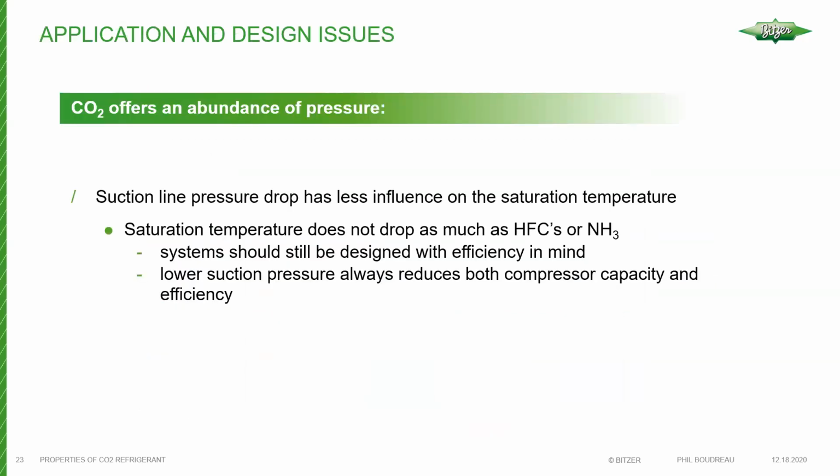CO2 offers an abundance of pressure, and that may sound strange, but over the next couple of slides it'll make more sense. Basically, think about it this way: suction line pressure drop is going to have less influence on the saturation temperature. We could see more pressure drop in the suction line before we see a drop in saturation temperature.